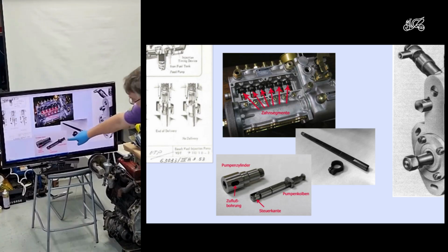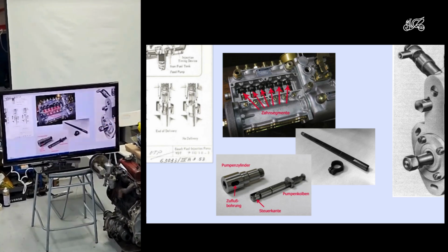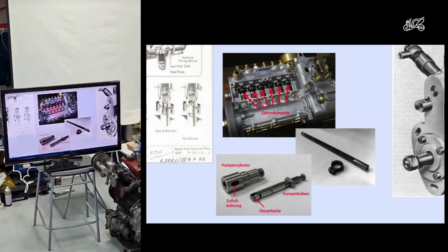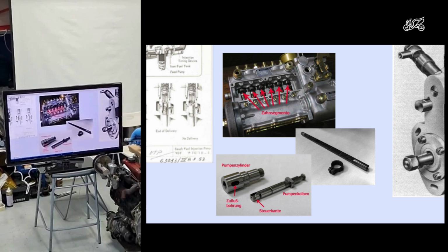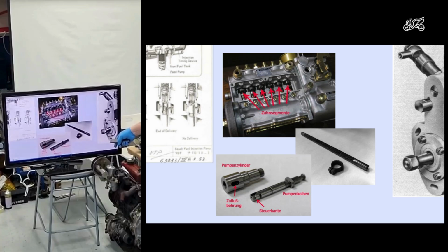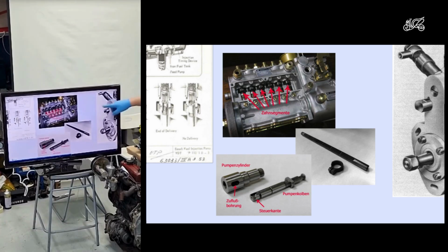And then there's a little piston inside this pump which is going up and down, and the piston has, you can just see it here, a spiral groove in the side of it, and the cylinder has got a hole in the side of it. And in this pump, just like a diesel pump, there's a rack, and each cylinder has got a little gear on it. And so with that information about manifold pressure, you're pushing this rack backwards and forwards. And as you push that rack backwards and forwards, you twist that cylinder.